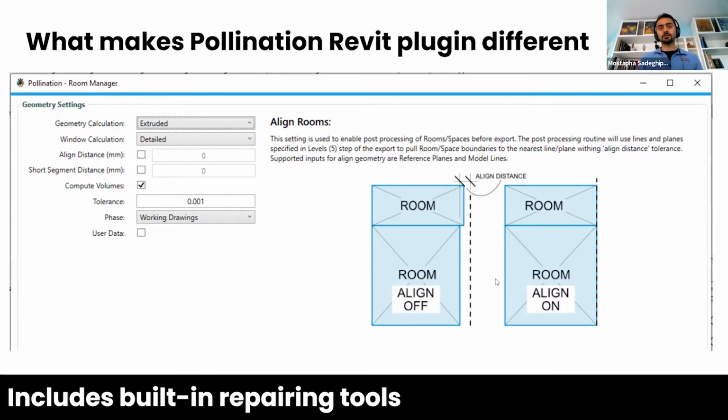The reason we had to do this is that there are a lot of Revit models we get where people use the separation line, or you have walls with different thicknesses. You end up with rooms that are slightly moved up and down. It's not necessarily a problem until it is. So if you want to clean them up, you can now do this without fixing the room.